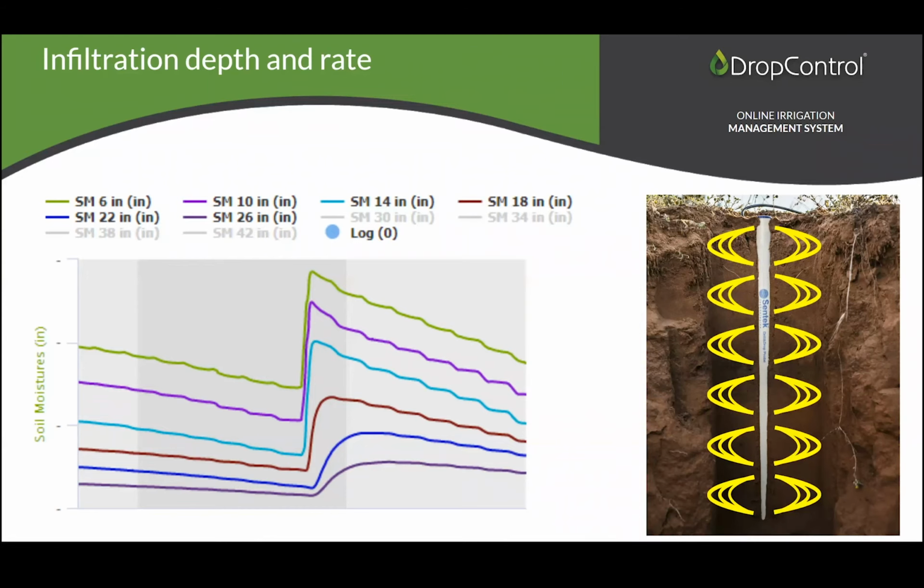We had a probe and we could see, based on the irrigation, that the probe was telling us the water was getting all the way down to 4 feet, but we went out there, augured, and the water was only getting down to 2 feet. What's happening is that the structure of that slurry was letting water by faster. So that is something to absolutely keep an eye on when you're choosing a probe and when you're installing the probe. And if you do choose a probe with a lower area of influence that needs to be installed with a slurry, then you need to keep an eye on those readings for the first few weeks.